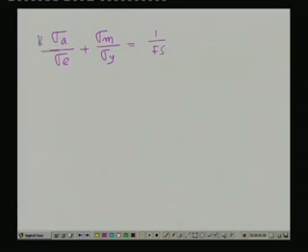So, what is this one? We know that sigma a, the stress amplitude, by the endurance limit, plus sigma m by the yield point, equals 1 by Fs. You modify the stress amplitude by the factor Kf. So, what is the stress amplitude? This is equal to 0, so this term is not coming into the picture.